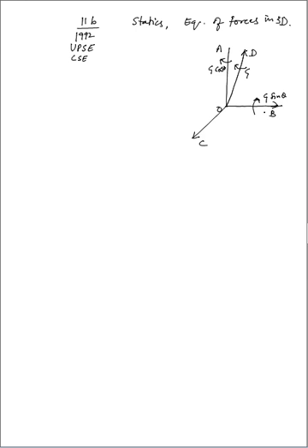So we can define it, and with the help of this we can derive that a system of forces acting on the rigid body is equivalent to a single force R acting along a line O dash A dash, and a single couple of moment G cos theta about the same line O dash A dash. That we can define, but here we have to define the central axis.